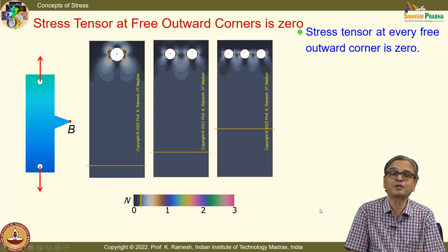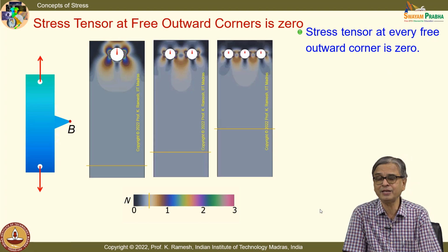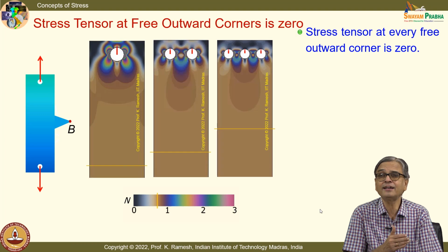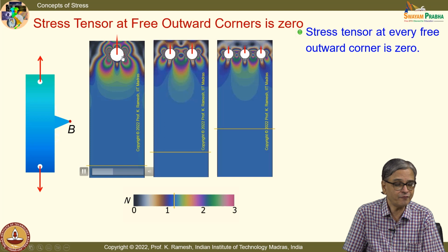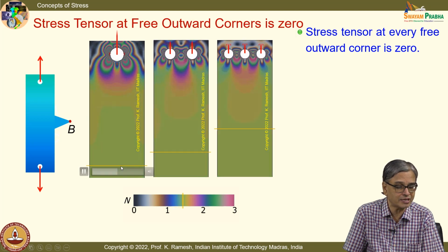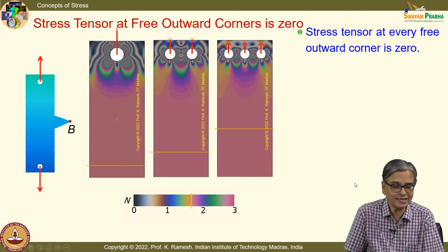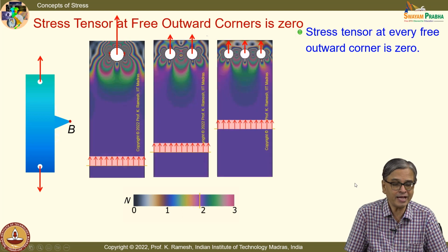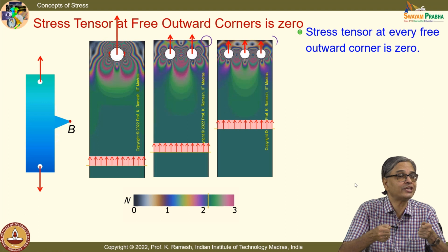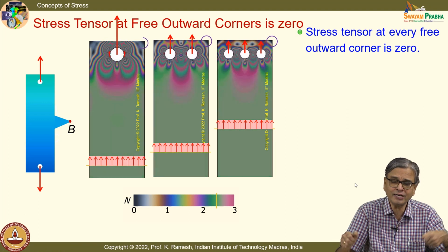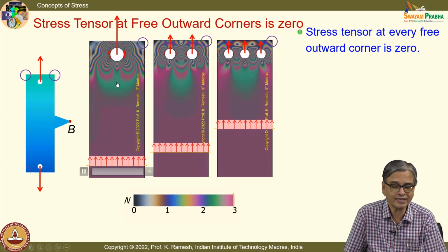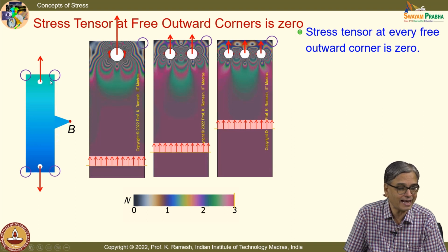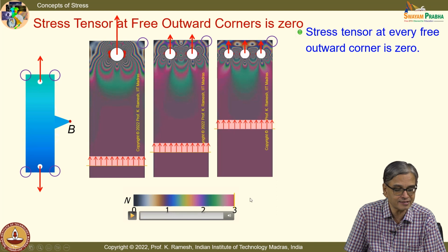I have taken this up because we have looked at what is the Saint-Venant principle, and that concept you should understand. If I have a resultant force that is the same, and I make my load application more and more equivalent to the distribution I want, the distribution becomes uniform earlier than the other case. But if you look at here, these corners are black. And what do you see black in this color code?